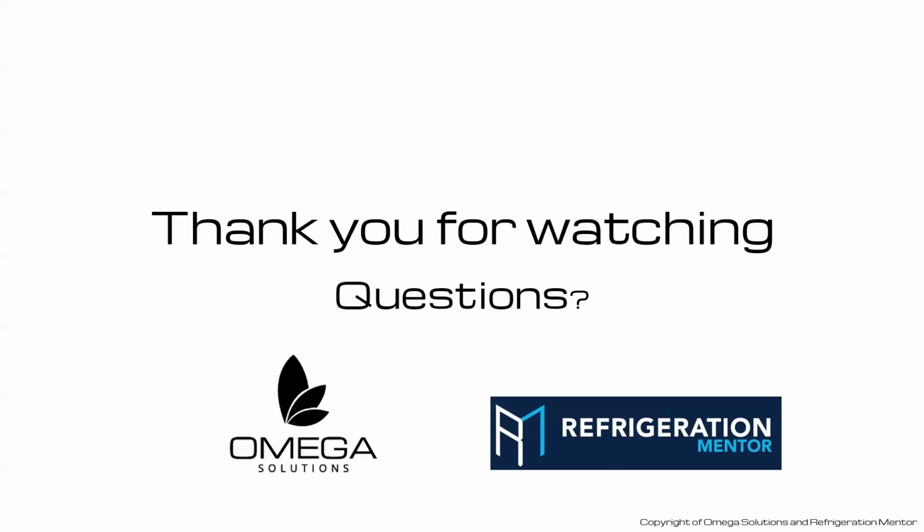And the other big thing was in the piping portion, as you talked about insulation and picking up heat. I've seen a lot of non-insulated drop legs from the condenser, whether adiabatic or otherwise, and you're picking up heat in that drop leg. And like you said, all that subcooling you're getting, depending on where your region is, gets wasted.